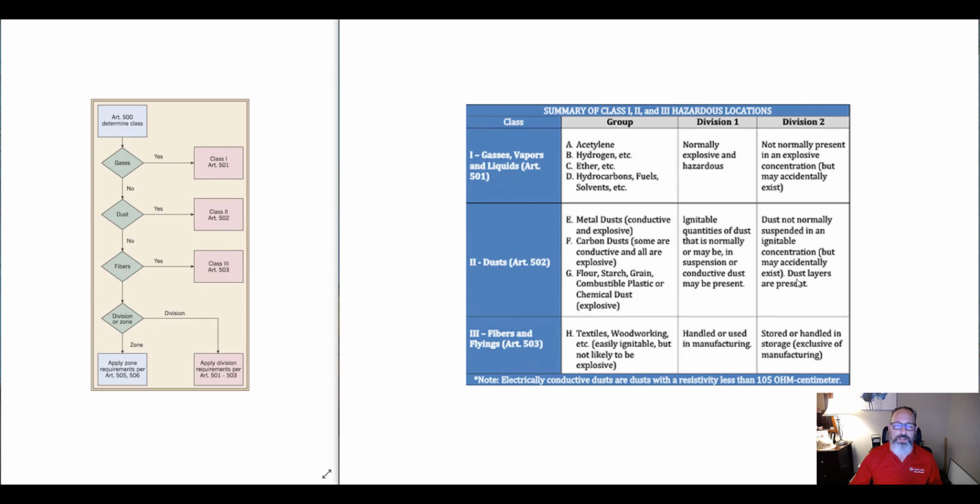Now, at the top of the silo, outside, maybe it's not Division 2. Down at the bottom, where the grain elevator is, or around the outside of the silo, possibly could be. Dust may come down and settle in the ground area, or where dust layers are present.